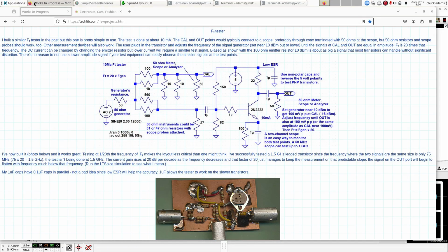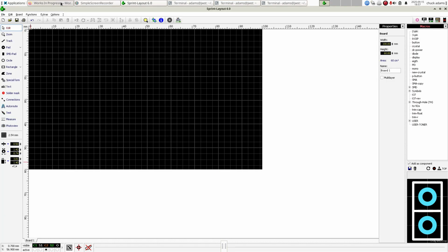Now let's go back to the schematic. Now what I do is I just lay the printed circuit boards and the components in the same order they occur on the schematic. So we're not going to do anything on the board for this other than I need an input pin, and I'm going to just lay all the components in this branch here in a straight line. And I'll start it out and I'll show you. And I'm going to alternate, hope you don't get sick, between the schematic and the layout program.